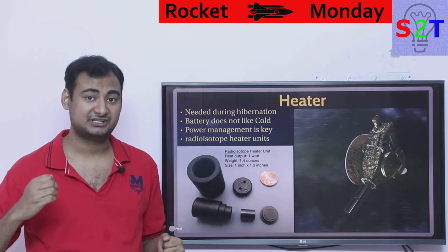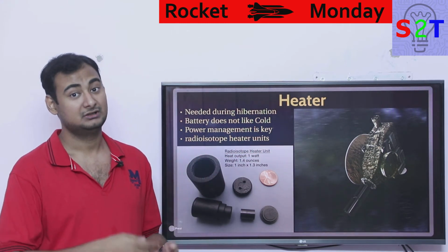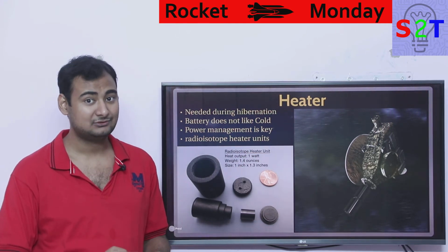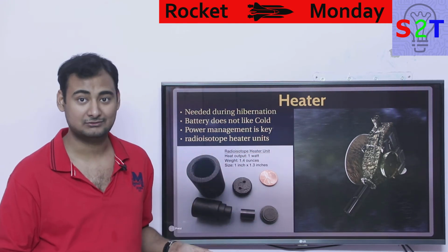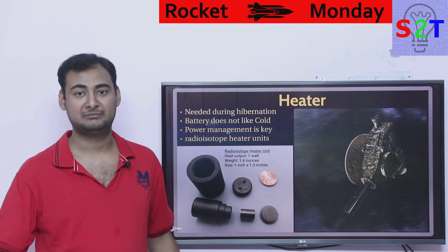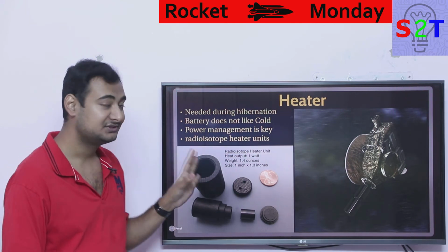It's not something where you can just say, okay, we're going to make sure it's always hot, because it's going to stop working, or we're going to make sure it's cold. Now, the processor will like the cold temperature, the camera sensor will like the cold temperature, most things will like cold temperature. Heck, we use liquid nitrogen for overclocking. But the moment it touches the battery, it's like, no, I'm dead. And thermal sensors also need a reference point. So that is why we have heaters.